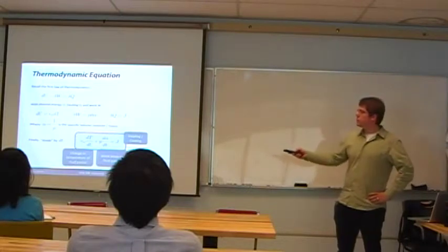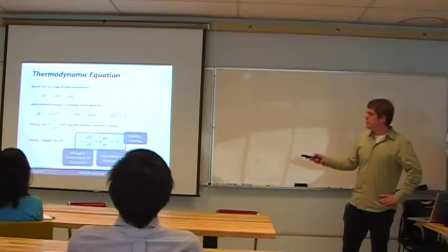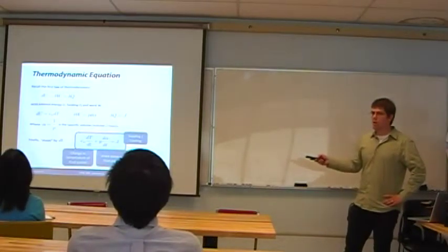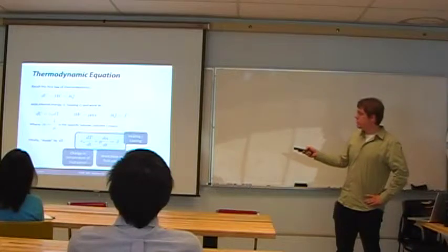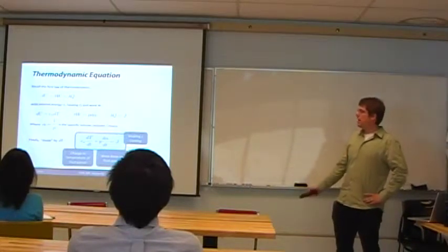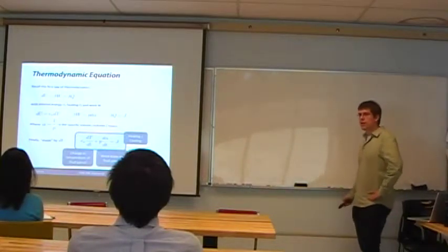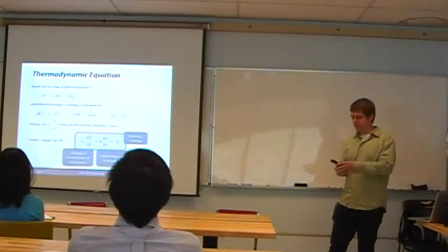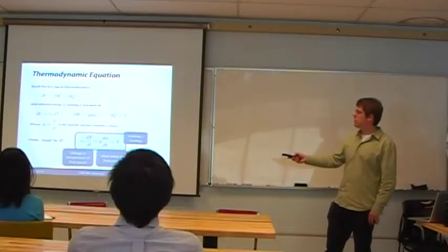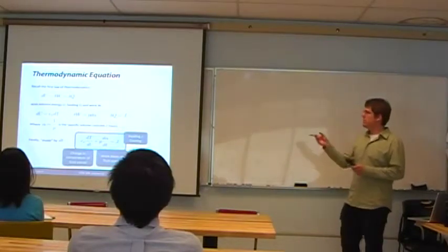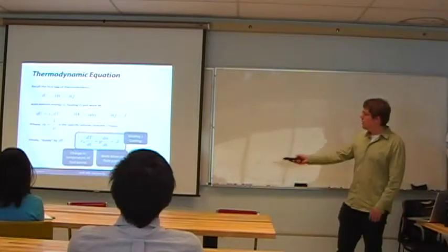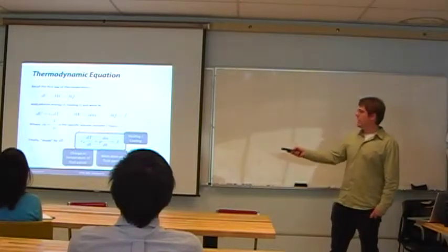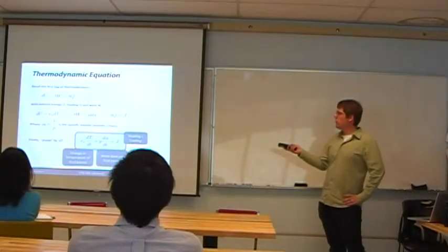So recalling then the first law of thermodynamics, we have a change in internal energy, du, minus work done on the fluid parcel, which is equal to the diabatic heating applied to the fluid parcel. So if everything was adiabatic, namely if there was no external heating placed on the fluid parcel, then this dq would be equal to 0, and the change in internal energy would simply be given by the work done on the fluid parcel.